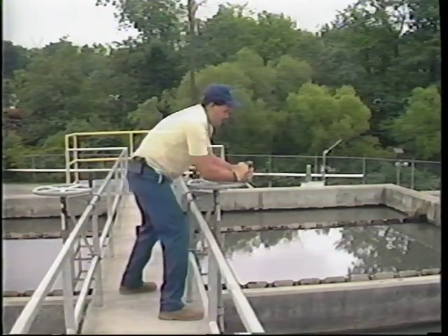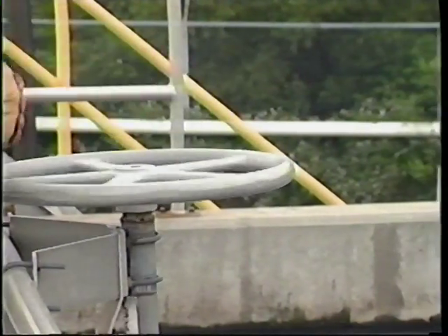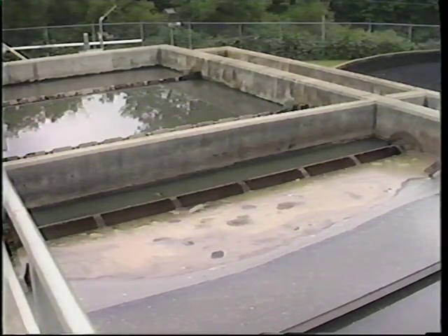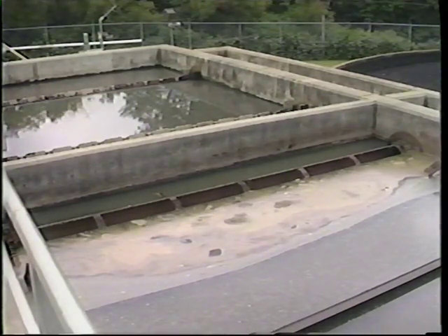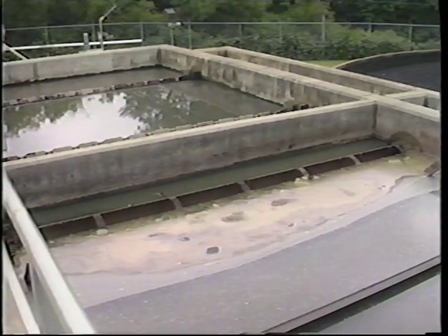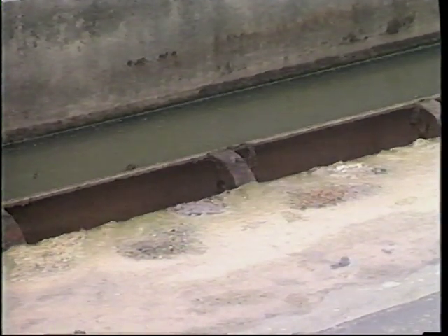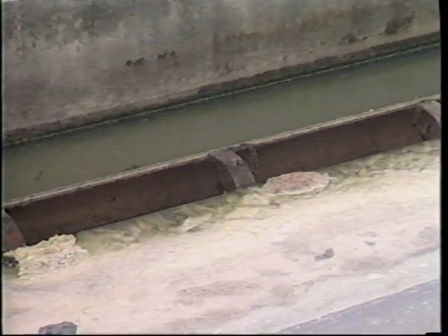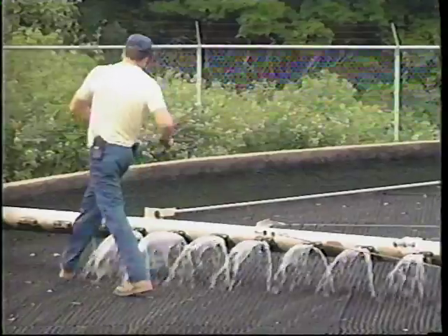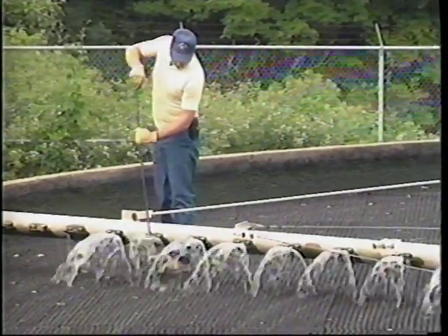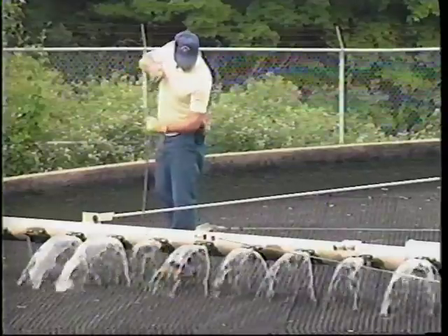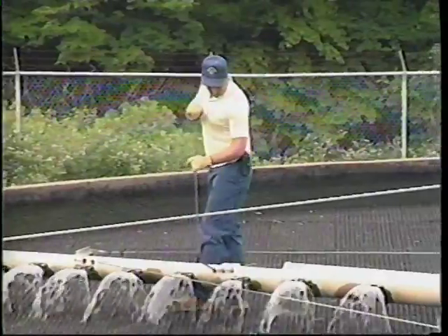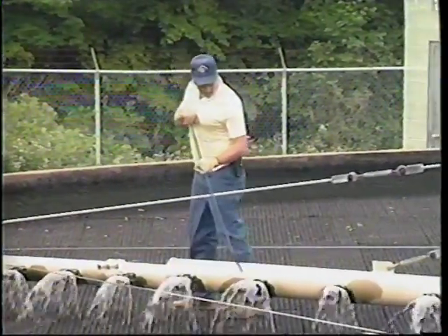The proper operation of the scum removal equipment is also an important element in the performance of the clarifier. Any problems with the scum removal process should be identified and corrected immediately. Timely removal of floatable solids or scum is an important function of clarification. If floatable solids are not removed, they will flow to the secondary treatment process or ultimately contaminate the facility effluent. This is a problem especially with trickling filters, as the floatable solids will clog orifices and media.